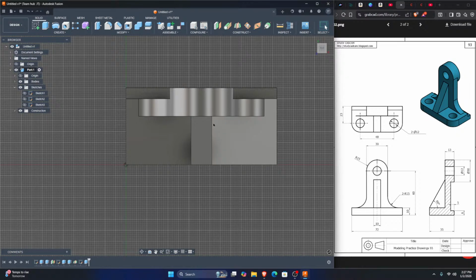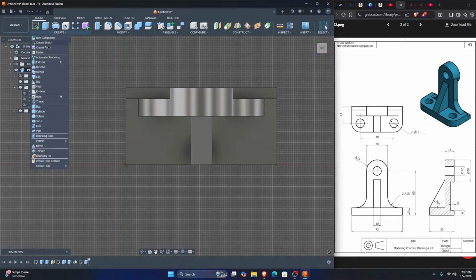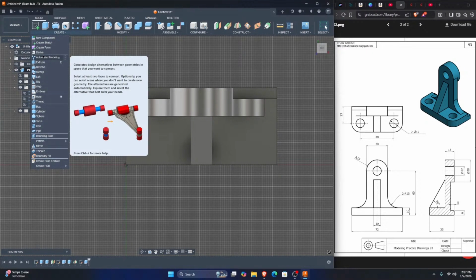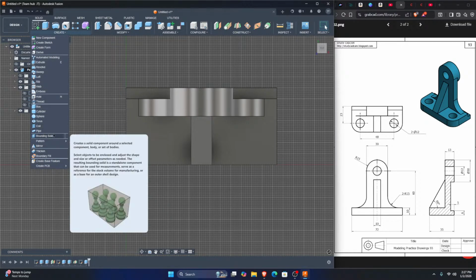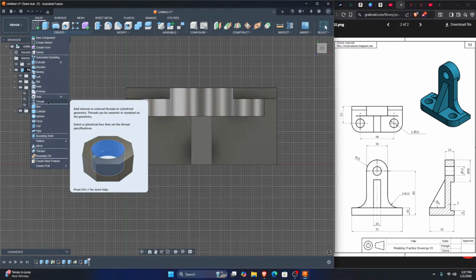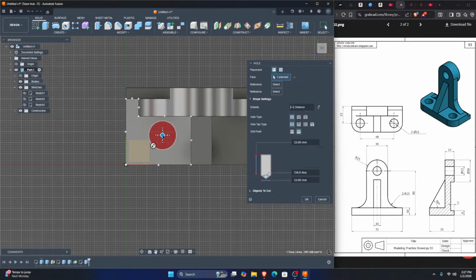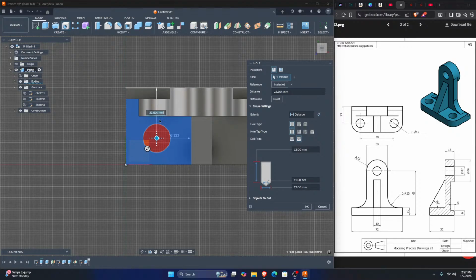drawing over here. So we can go ahead and go to our modify tab, our 3D create tab, drop down. We'll go ahead and reference, where's the hole? Here it is, hole H. I'm going to put it on this profile here. And there is a way where you can reference corners. So I'm going to reference from this one here. It's 23 millimeters, so I'm going to specify 23.